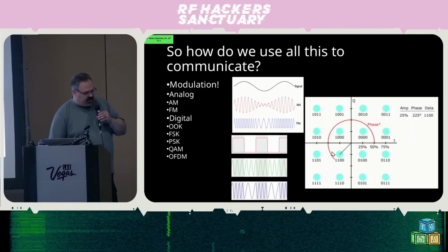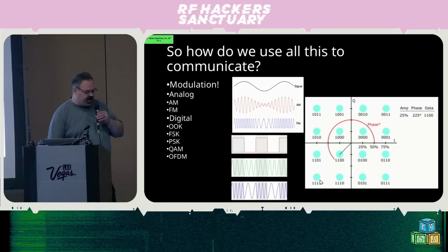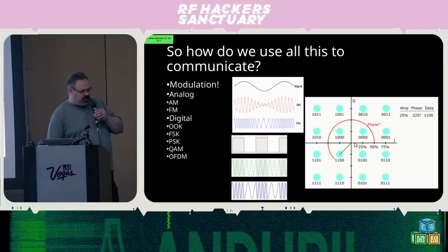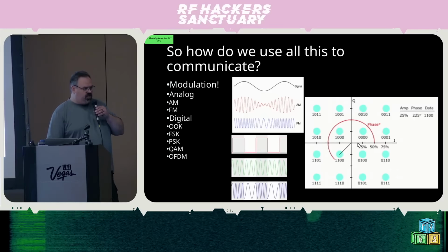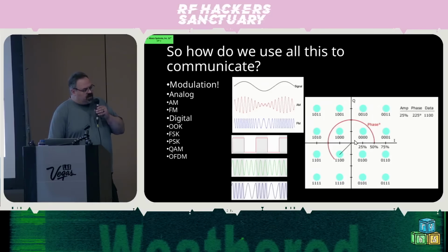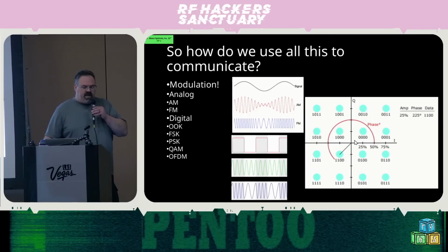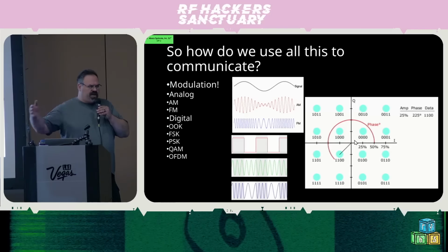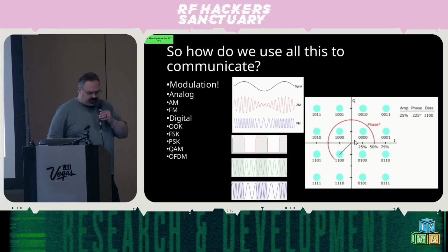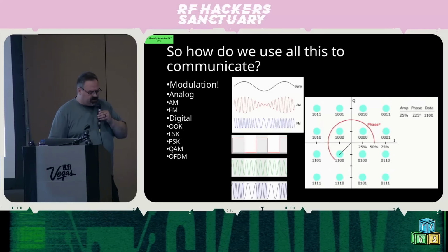And yeah, the encoding of each of these is based on a different IQ XY coordinate. And it just kind of lets you pack a lot more bits into your signal that you wouldn't have been able to before. The downside is you need a much quieter channel in order to get this to a point where you can decode it. Otherwise, it all just looks like noise.